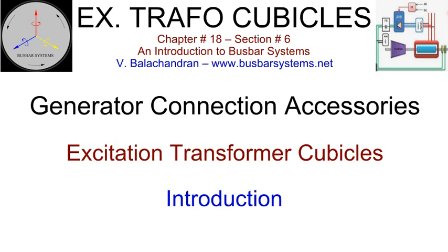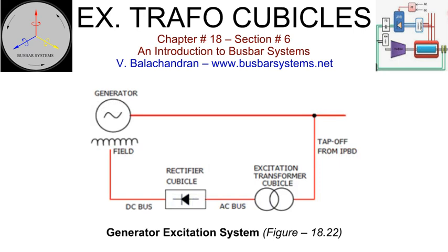The conductor is connected to the terminals of an excitation transformer cubicle with a flexible connector. When the prospective fault currents are high, no protective device such as a fuse can be installed. The excitation system comprises a dry cast resin, 3-phase transformer.